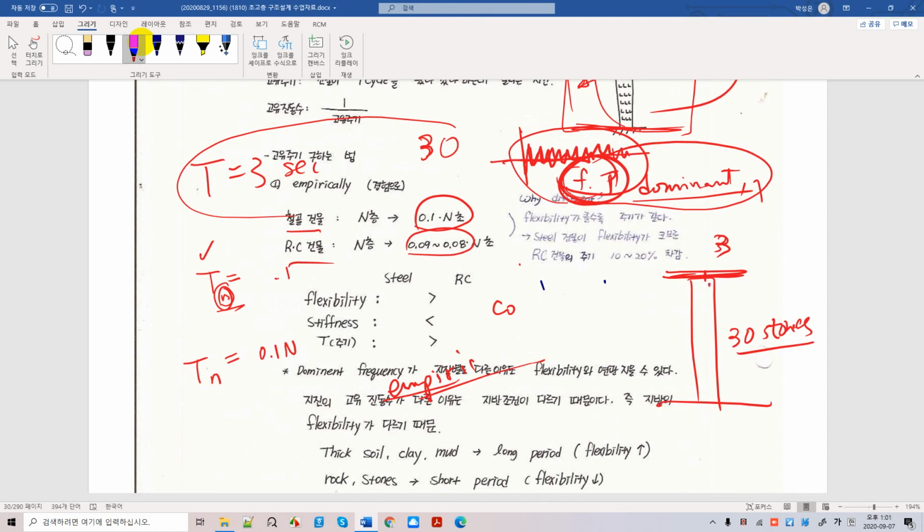And if you have a concrete 30-story building, maybe 2.7, 2.4 seconds. Right? How accurate it is, I don't know. It is accurate based on empirical experience, and empirical experience hardly disappoints you, which means this formula will bring pretty accurate solutions for you before you go into Midas. So that Midas, this is very interesting.